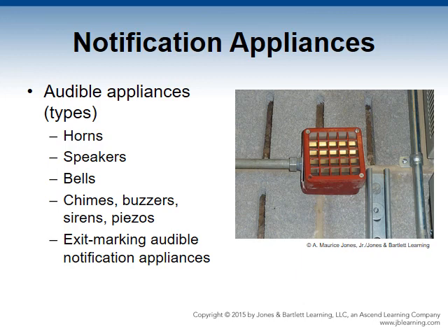Speakers are the most versatile audible notification appliance because they can reproduce many different sounds in single devices. They are mainly used in high-rise systems and sound the 3 pulsing temporal pattern, a pre-recorded voice message, or a live voice message. Digital technology has eliminated the need for tape players and other outdated technology subject to mechanical failure. Speakers are usually ceiling mounted and driven by a remote source and amplification equipment, or integrated source and amplification equipment.